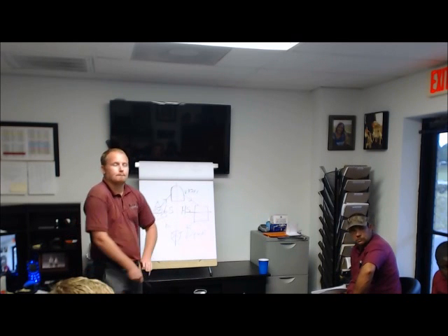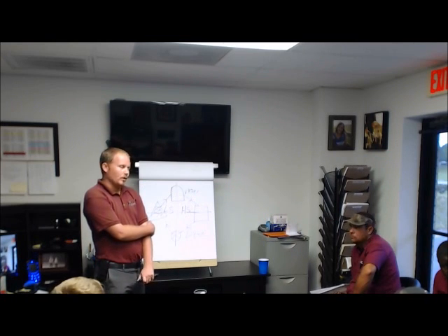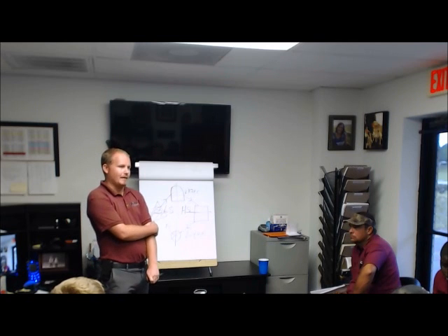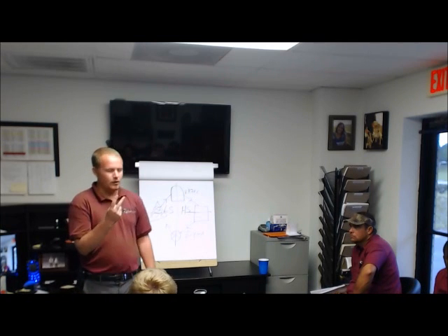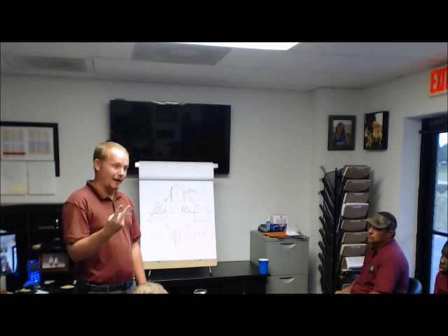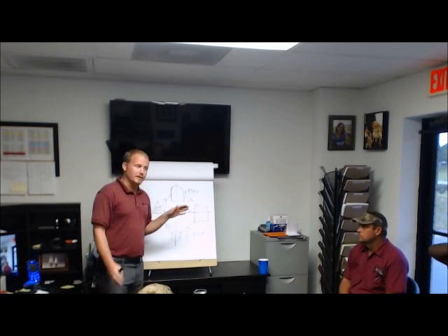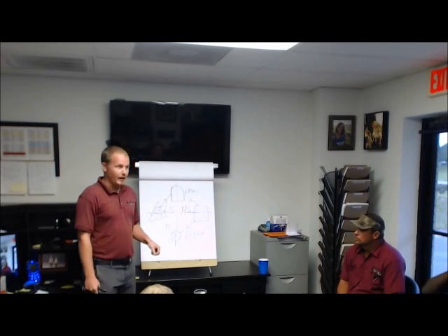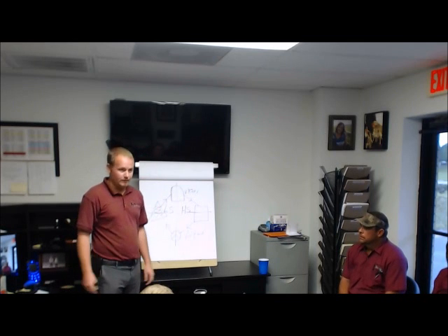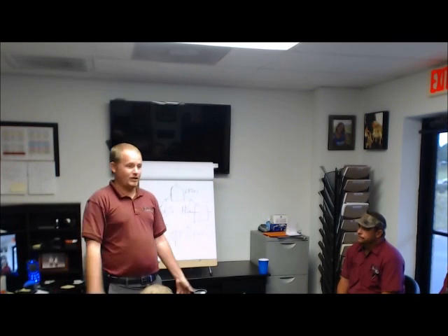Okay, so on that evap coil, is it the amount of refrigerant that's telling you at what point it changes state right there? It isn't just that. You've got two different factors here. You've got the volume of mixed refrigerant that's traveling through it, and you have the amount of heat absorption going on around it, which is the reason why if you take an evaporator coil and you throw a bunch of cat hair on it, what does it do? What does it do to the pressures? You guys know because you work on it every day. You throw a bunch of cat hair on a coil, what does it do?